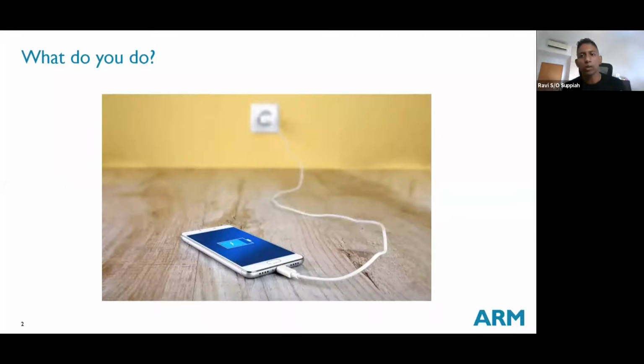You're driving your motors later on, you write the code, you run it, your motor is not spinning. Okay, the first thing I'll ask you is, have you confirmed that the PWM signal is in fact coming out of the pin? All right, and to do that, you must use your oscilloscope. All right, so these are things you have learned before in EPP1, EPP2, so you need to apply that knowledge here. Okay, so if the motor is not spinning, check the PWM first.